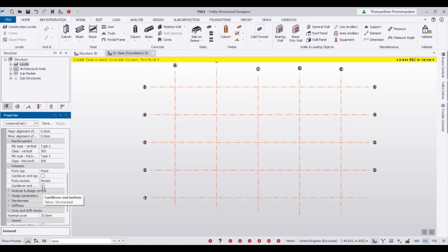So let's say these types, right? If you don't do the proper analysis, if you don't do the proper stiffness reduction, right? Then the main beam carries the torsion, which is very dangerous. I saw many models, people model it without understanding, so the beam carries the torsion.